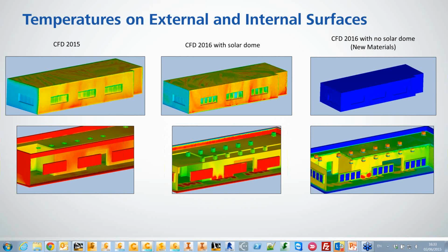That can be very impactful if you're considering where someone's going to be in a room. You can take a beating from the sunlight in a corner, or previously if we had a room with a lot of windows around it, maybe you would get very hot, and that could be something you may want to consider while you're doing an HVAC layout, because if you're not properly cooling that corner of the room, the solar light is going to give people a sunburn, and it's going to be just too warm.